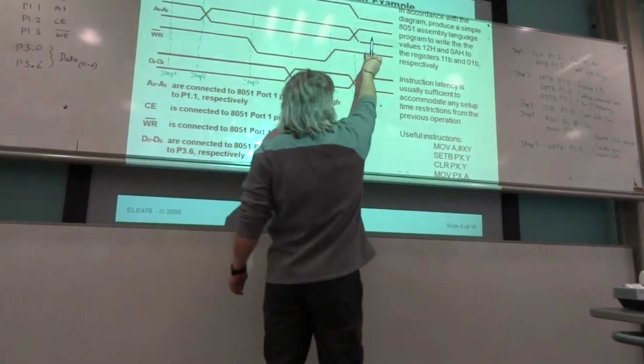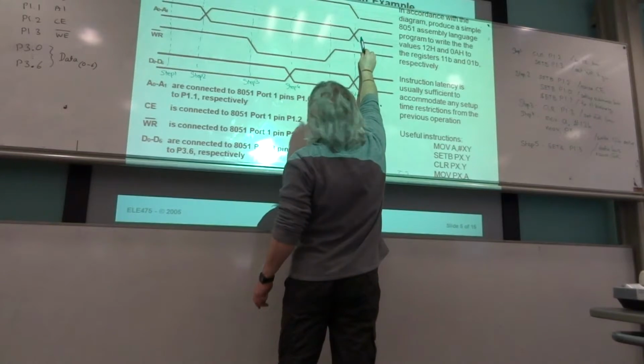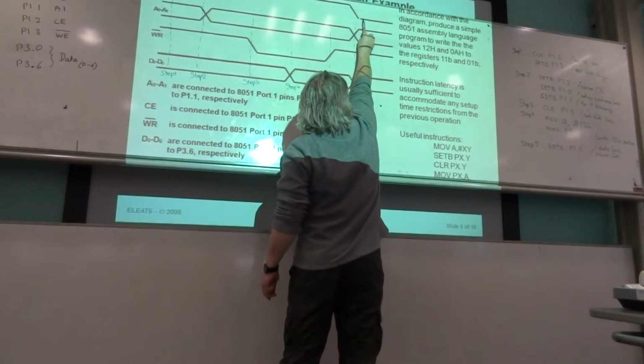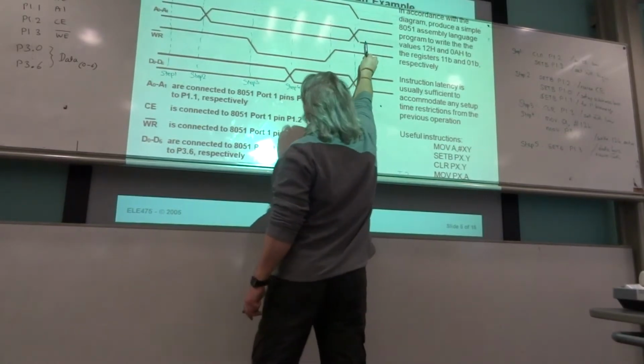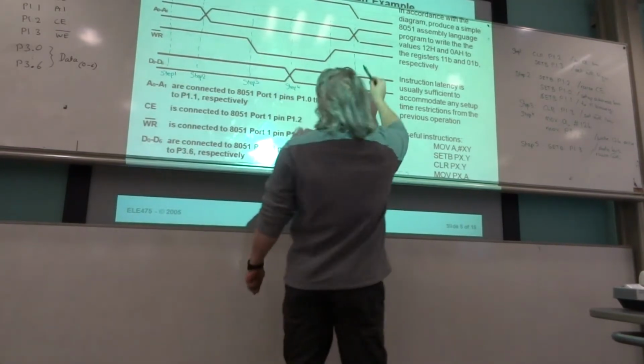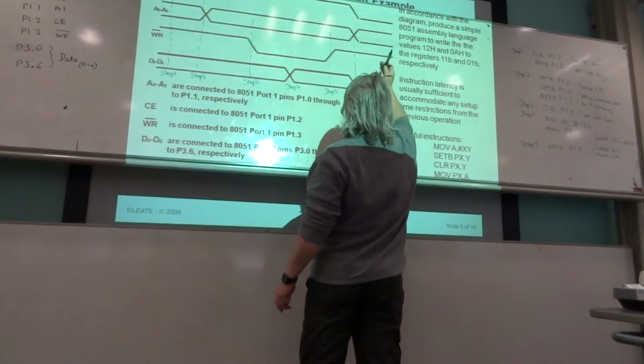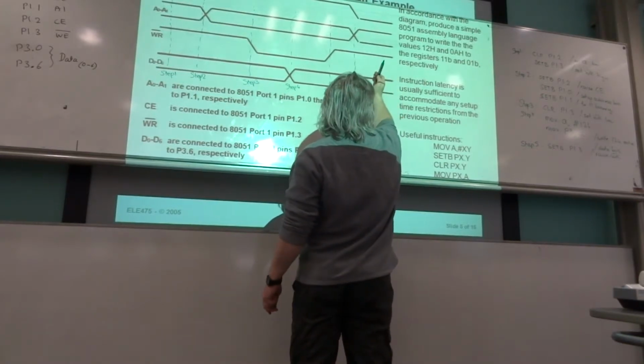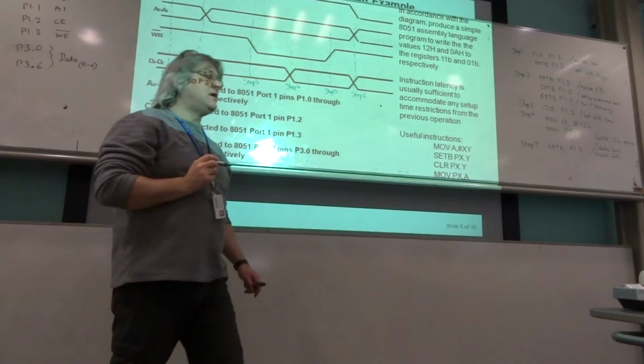we can start with changing, there's a whole set of things happening here. We're setting chip enable low, we're starting to prepare the address bus for the next cycle. This will all have been raised, and we're setting up the data ready for the next cycle.